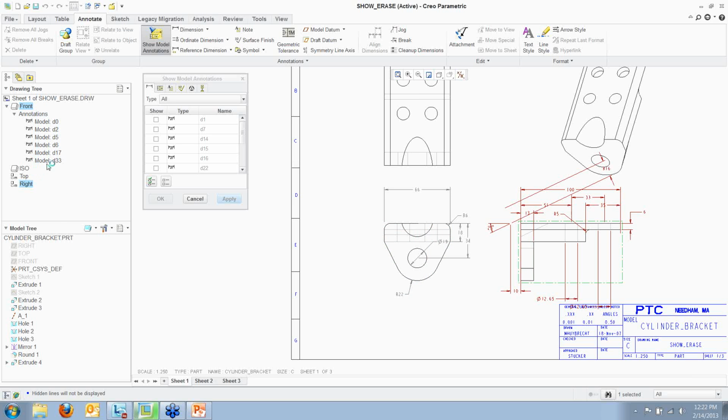So once I select them and I put them on the sheet, they're no longer available to be placed somewhere else. That allows us to quickly place things, and once I start placing them, good working practice is never to show a dimension twice on one sheet. In 2 different views, you always want to only show it once. Otherwise, you're going to clutter up your drawing sheet with many dimensions that are not necessary.